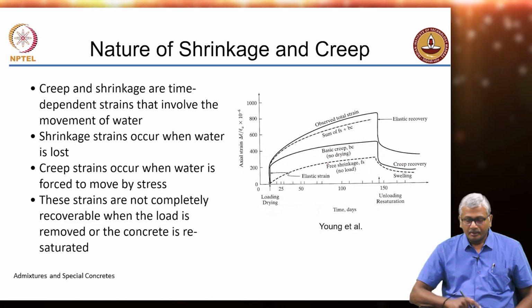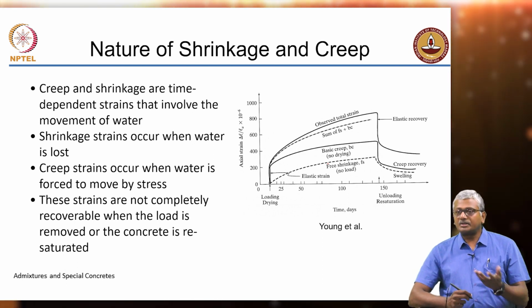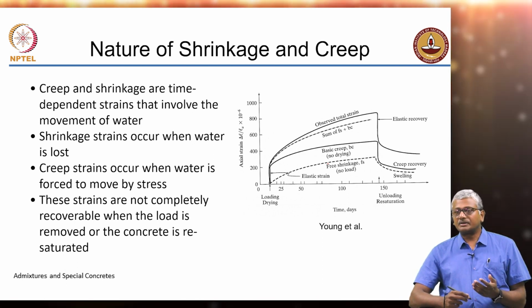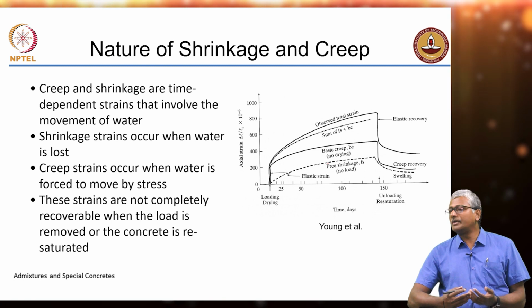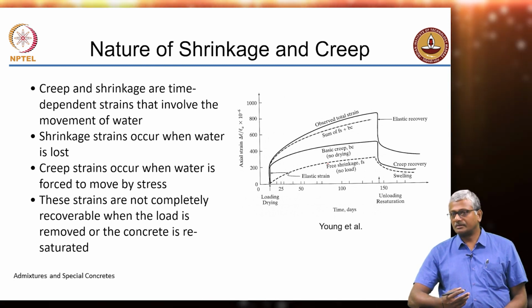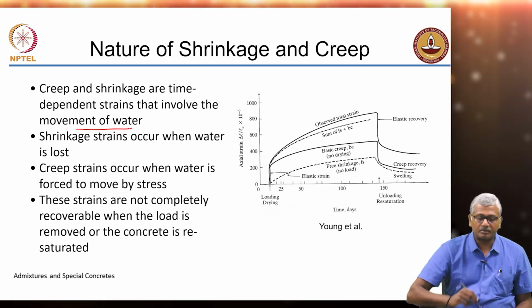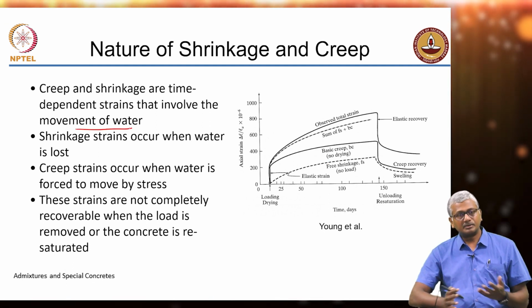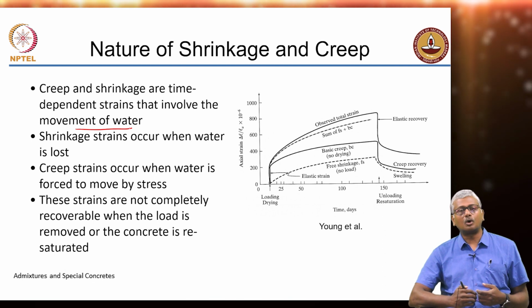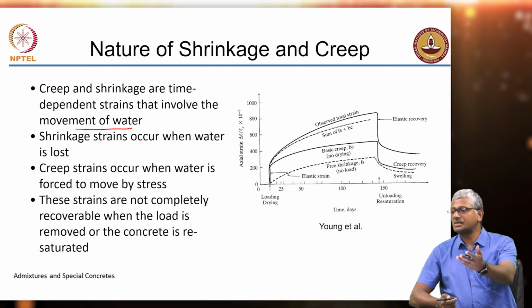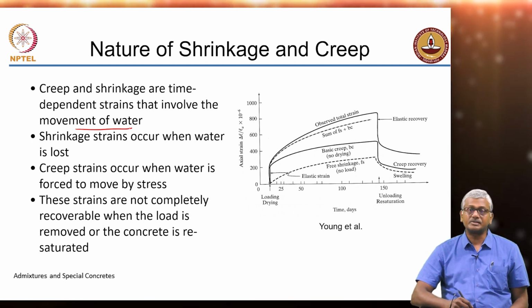Anyway, what happens in the long term is that concrete behavior is subjected to time dependent deformations, okay. Primarily it is because there is water inside the concrete and this water will move when you keep the load on for a long period of time, just like the consolidation in soils, right.